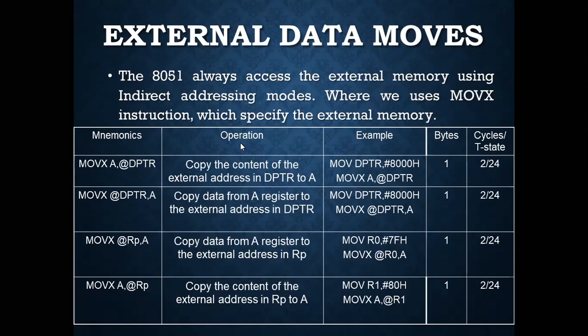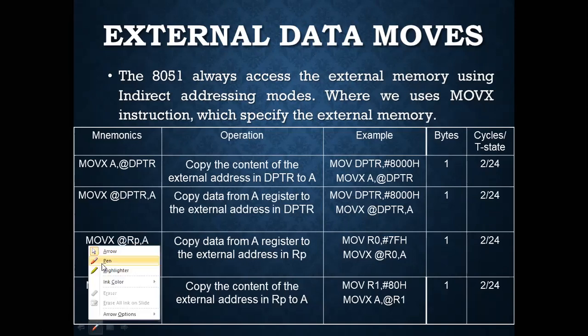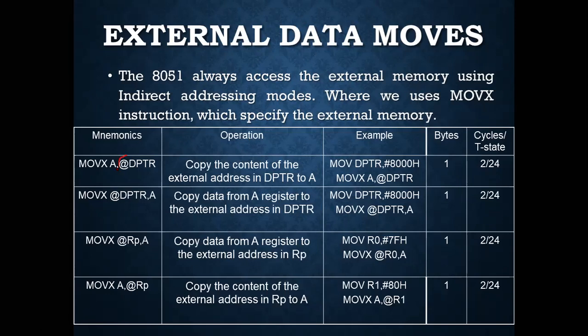We have discussed in earlier classes that whenever this at-the-rate notation is there, the content of the DPTR will be acting as the address, not the address of DPTR.